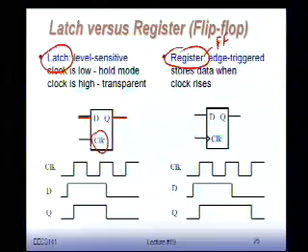Okay? Now what the latch does is the following. The clock really is nothing else than a gating function. If the clock is low, the output Q will remain constant. It'll just remember its old value. However, when the clock is high, the input will just propagate to the output. So you have two modes. Clock is low, we hold the value at the output. We just store the value and keep holding it. When the clock is high, we feed the input to the output.